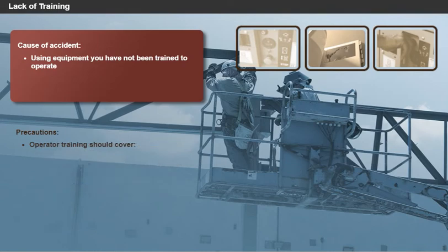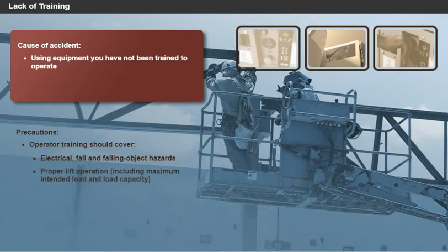Operator training should cover electrical, fall, and falling object hazards, proper lift operation, including maximum intended load and load capacity, and manufacturer requirements.